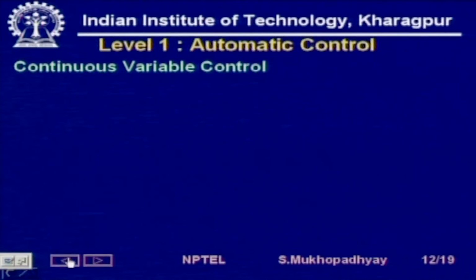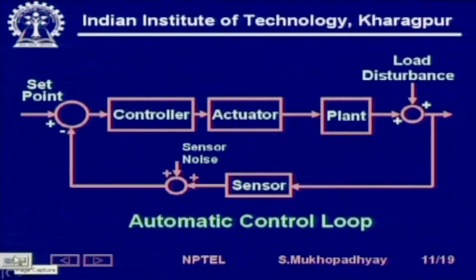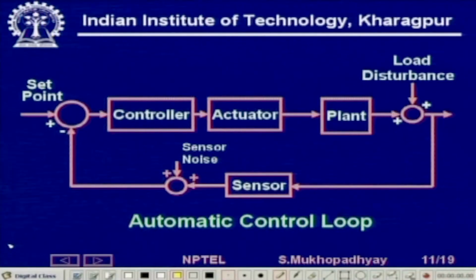Let me go back. Let me lock this. So, the job of the controller is to maintain the set point, that is its job, which comes from the supervisory control. So why should the set point change? Why is it, once I set it carefully, why should it change? It changes because of disturbances.